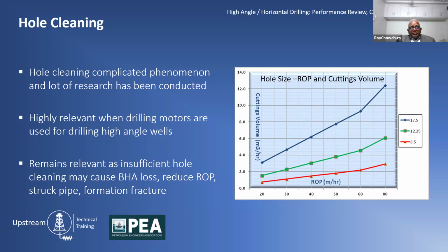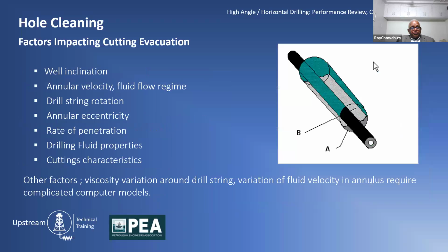So it is extremely important to understand that hole cleaning is very important. Otherwise, it will compromise the rate of penetration. It can have a BHA loss, stuck pipe, and many other issues. Now, what are the factors that dictate the hole cleaning?